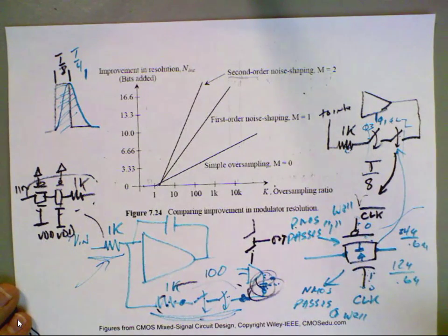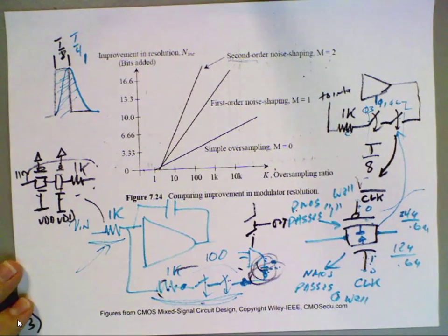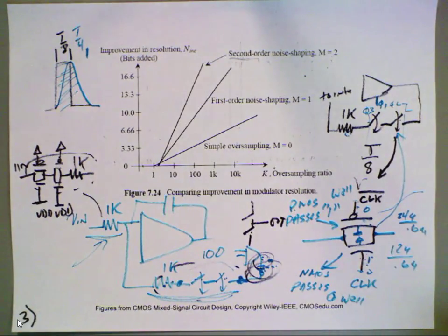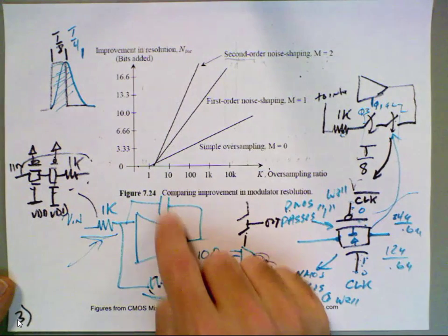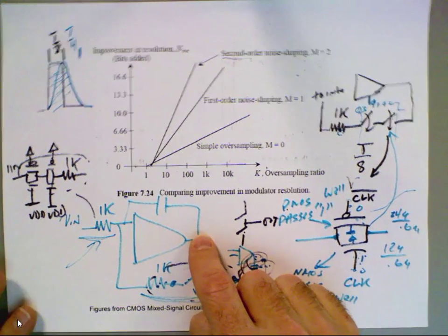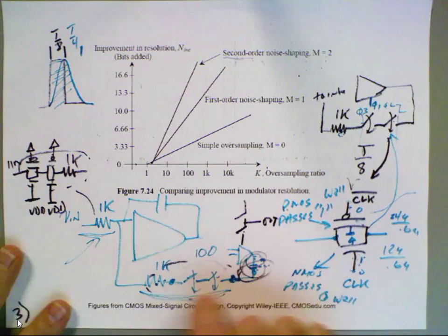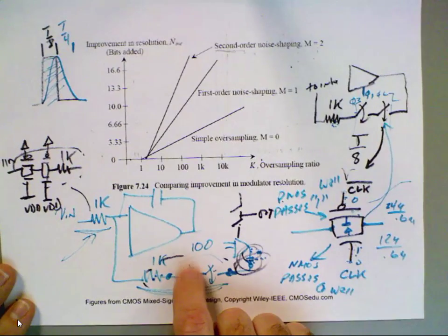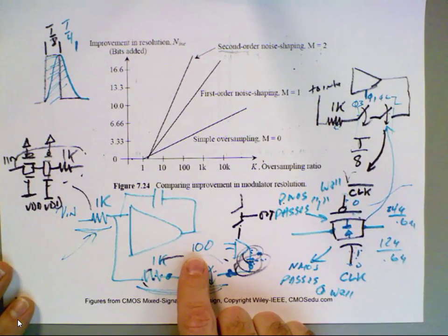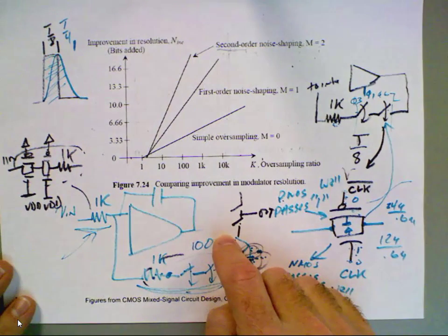So yeah, then you have to increase the integrator capacitor so you don't saturate on your output. But I'm not saying real slow, just slower. You don't want the capacitor to be too big because then you get less swing here. I don't know why you're not getting swing, but it's easy to see if you're not getting swing. This node goes high, low, because that means it's unstable.